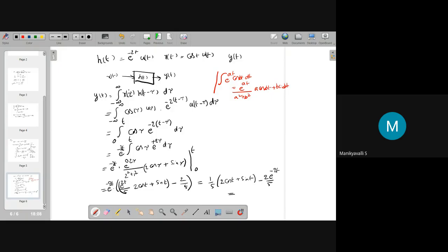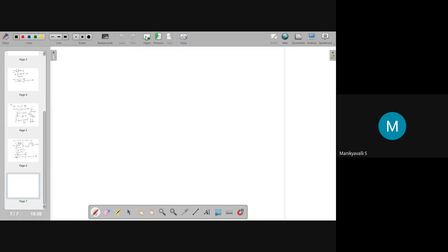So now you should have understood how painful this convolution is. It takes a lot of time to integrate and do signal shifting operations. So we'll have one better approach than doing convolution in time, which is the frequency domain. Doing the same operation, finding the response of the system in the frequency domain for a given input signal in the frequency domain, will give you much more benefits, especially computation-wise. In that case, one tool which we learn here is Laplace transform.